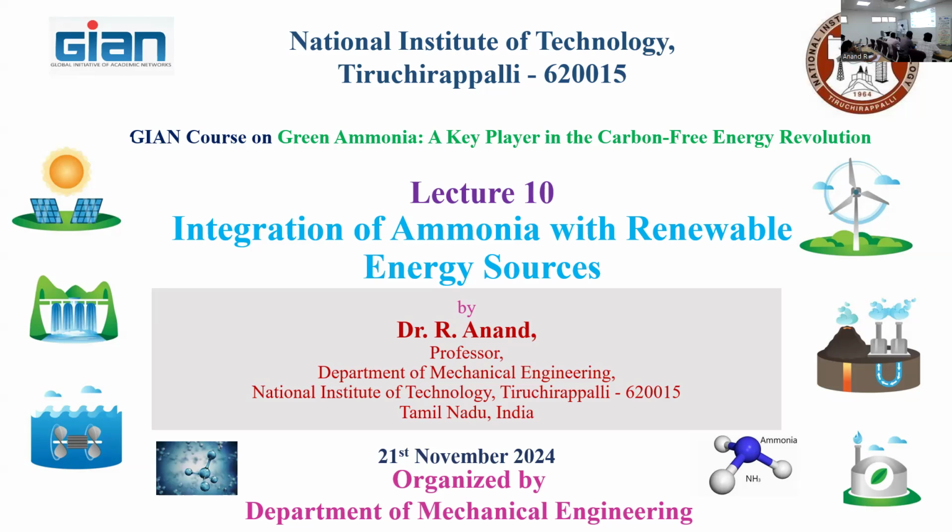Here, superheated vapor is entering. Superheated vapor means the fluid has a temperature more than the boiling point corresponding to the pressure. We call it the superheater, something like the man and Superman, right? Everyone has the same figure, but Superman has extra power. We can see that in the movies also. Similarly, this superheated steam has more energy than the boiling point corresponding to the pressure. So the temperature will be higher than the saturation temperature.